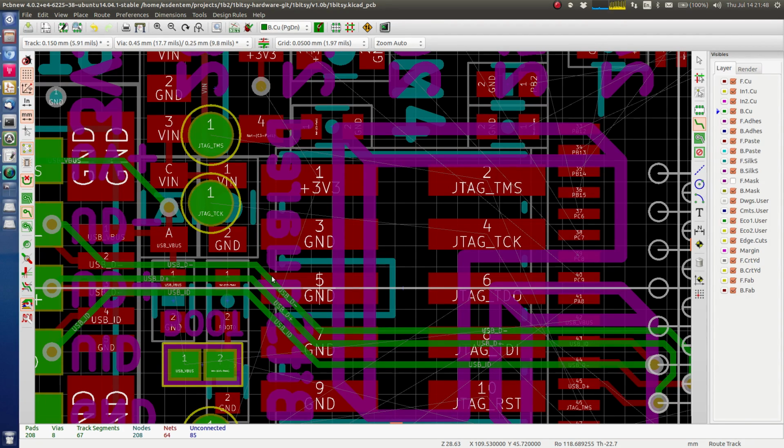The disadvantage is that every time you plug in a USB wire, the chip will go into bootloader mode. So it's a trade-off. With the JTAG, you can program it whenever you need to and use the USB port for everything. And if you want to flash once and then use a different power supply, or remove the jumper, you can.